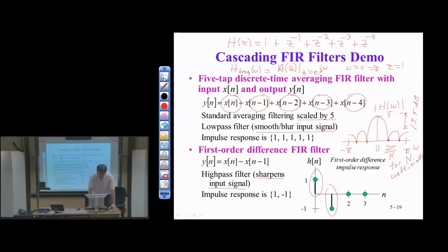So when I apply this averaging filter along each row of the image, I'm going to need 3 additional bits to store the results of that filtering without losing any precision. And then if I take that intermediate image and filter along the columns, I'll need another 3 bits to store the calculations exactly. So the application of the averaging filter along each row and then down each column, I'll need 6 additional bits. And then the first order difference along each row and down each column, I'll need 2 additional bits. So in the end, I need 8 additional bits from what I started with to get exact precision in the result. I started with 8-bit numbers. I'll need 16-bit numbers in the end without any loss of precision.